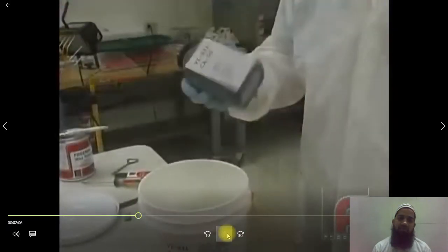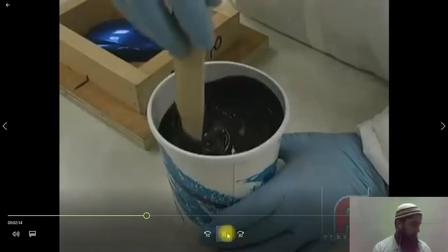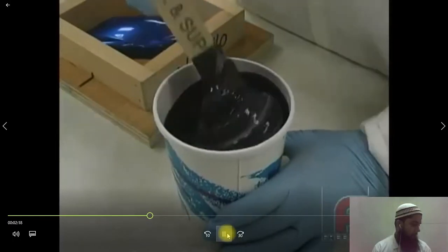After the catalyst is shaken inside its bottle, we are mixing 10 parts base to 1 part catalyst by weight, and here is what the mixture looks like. For more information about weighing and mixing, please see our other video on this topic.